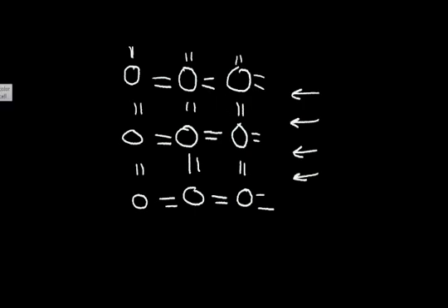For example, if we introduce a boron atom, a boron impurity, into this location, the boron atom doesn't have 4 electrons in the outer shell. It only has 3. So we could remove one of these electrons. Now what can happen? In this case, we have an unstable condition. The electron from this atom can go over and fill this spot and leave a vacancy here. Then an electron from another location can move in and fill this vacancy, and so on. So instead of having an insulator, we end up with charge that can move around. We end up with a conductor. And the more boron atoms we add, the more conduction is allowed.